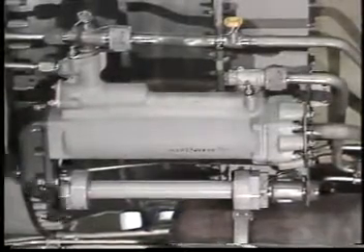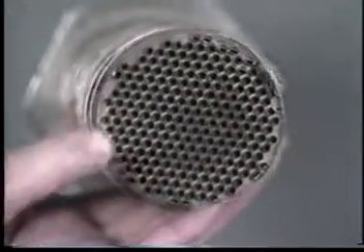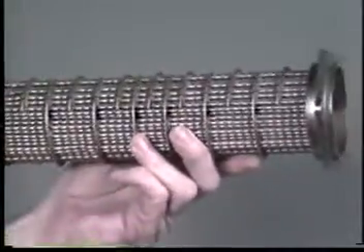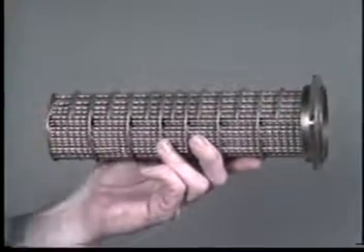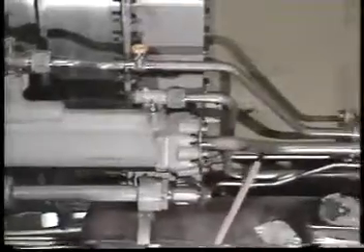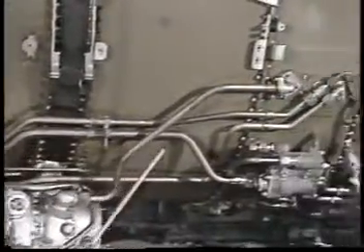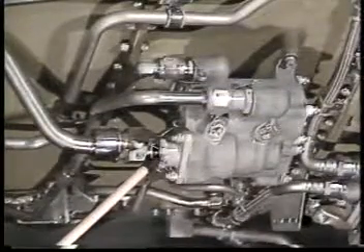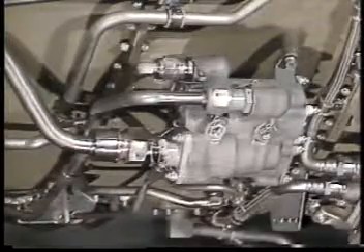The fuel oil cooler is a core tube heat exchanger. The fuel flows through these tubes and cools the oil, which flows around the outside of the tubes. The fuel then flows on to the pressurizing and dump valve. The valve overboard dump port is plugged to meet environmental regulations. Now the component functions only as a fuel flow divider.